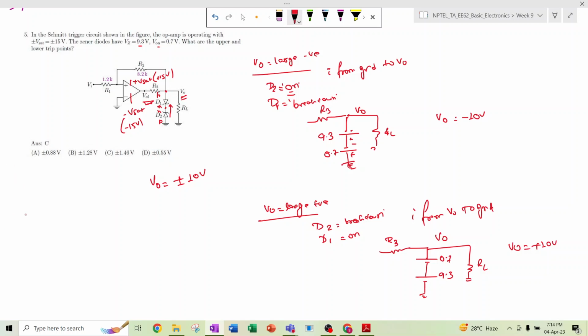So now we generally solve this question. Here similarly V minus is equal to 0 volt in this op amp, this is V minus, and what will be the V plus? The V plus will be, by using superposition you can find out easily V plus. This V plus will be Vi into, using the voltage divider rule, R2 divided by R1 plus R2, so at first we are considering this VO to be ground and Vi